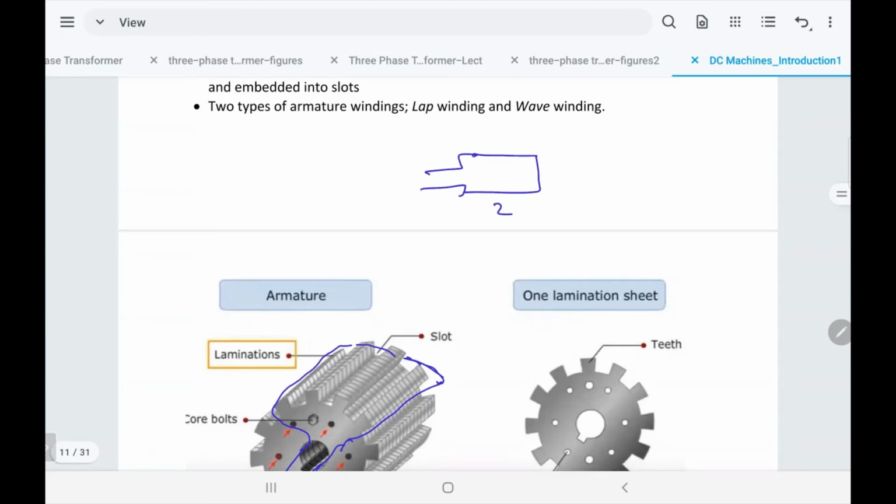They will tell you how many coils per winding and the number of windings, and then you can multiply and get it. That's why it is very important to know the terminology used: turn, coil, winding. So if you know the number of coils per winding and the number of windings, multiply by 2, then you get the number. Any question?